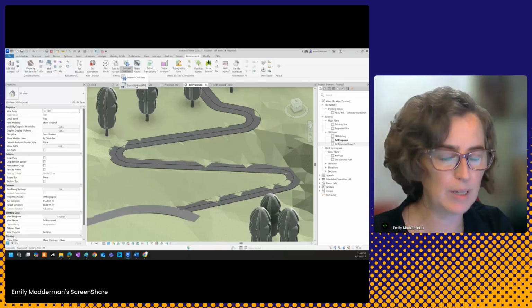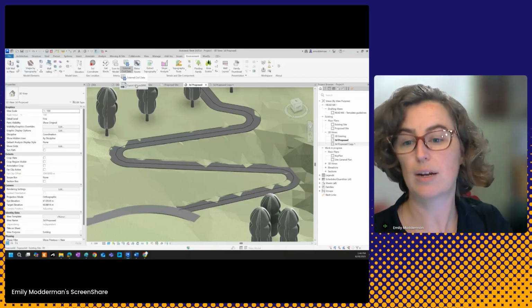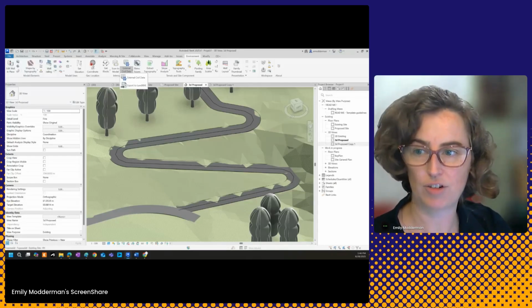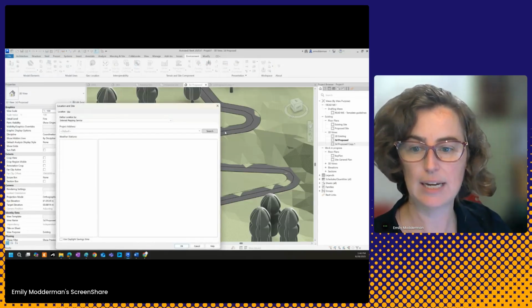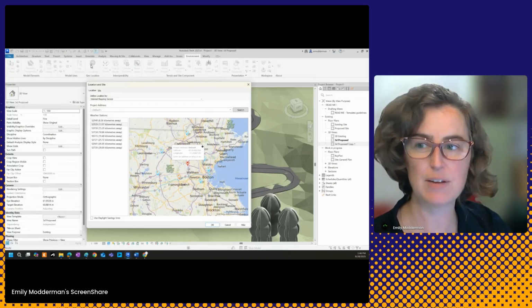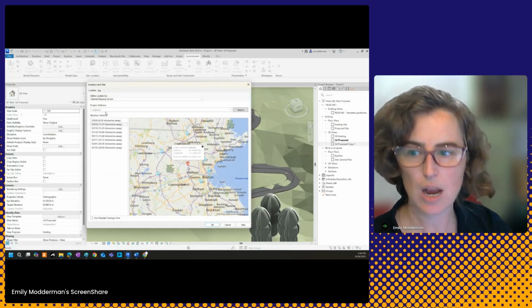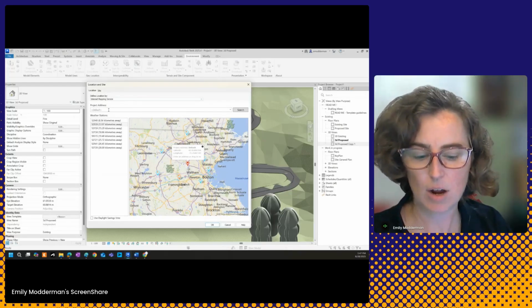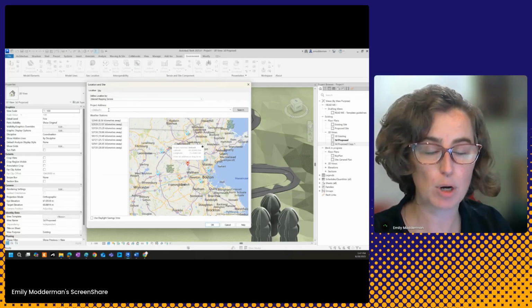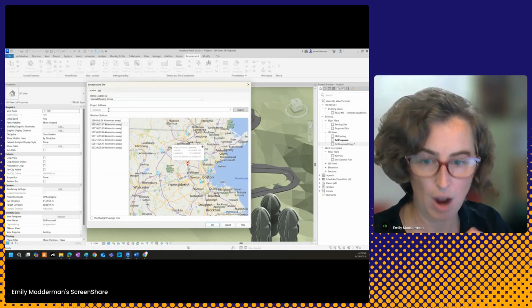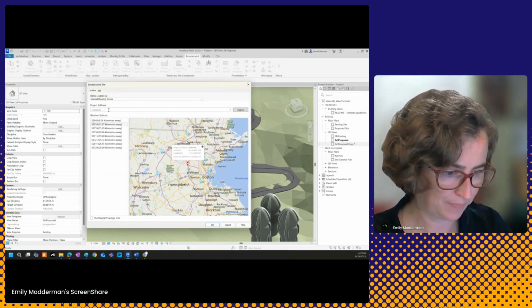And of course, we will always be linking. We will always rely on a Civil 3D geolocation, although there are geolocation tools in Revit that, with the aid of the environment for Revit tools, are getting better, and they're going to help us not only set up our shared coordinate location, but configure that shared coordinate with the geolocation of the site as well.